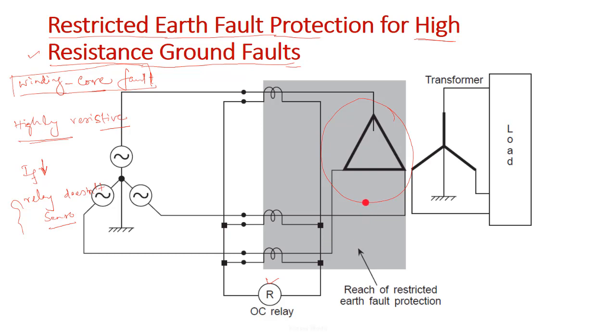Suppose we check how it will operate under normal operating condition, and how it will operate under fault condition. So under normal operating condition, obviously when the current flows here, the currents are flowing in this direction in each phase, and therefore your CT current will be out from the dotted terminal, and therefore here it will be the sum of the currents IA plus IB plus IC.